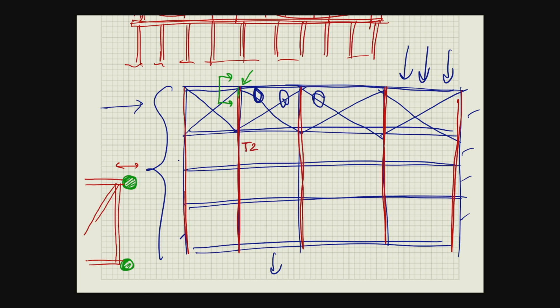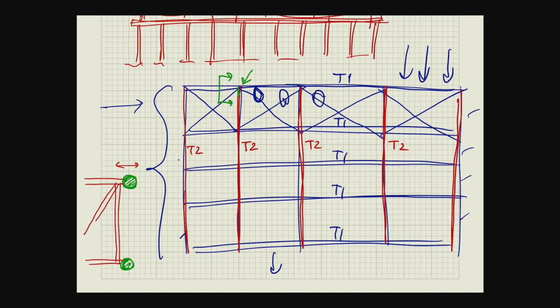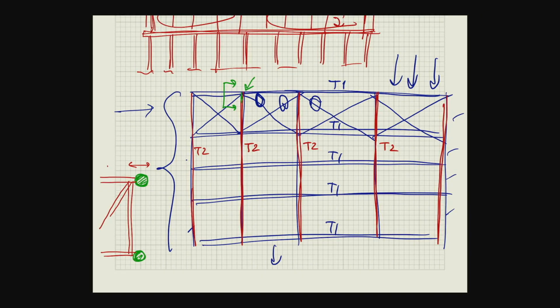In the design business, people always call it this way, T1, T2. And people will just understand that T2 is like the secondary truss that is used for the stability. So this is the T2. The green is the T1. So we need to restrain the T1 truss chords such that it doesn't move, and that T1 is going to mobilize the full bending, full moment carrying capacity.